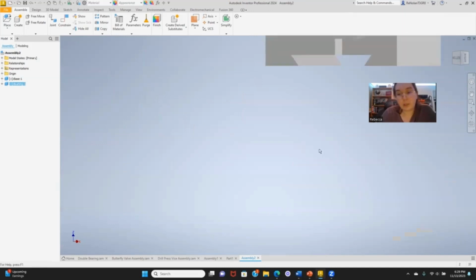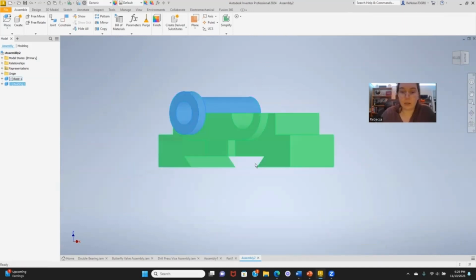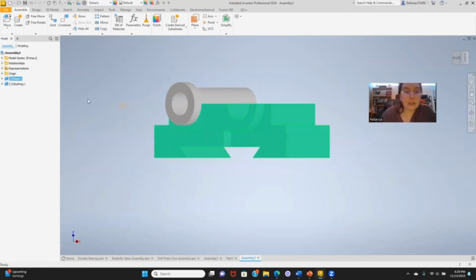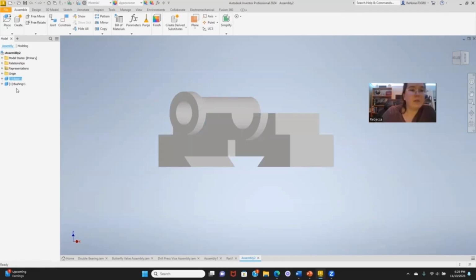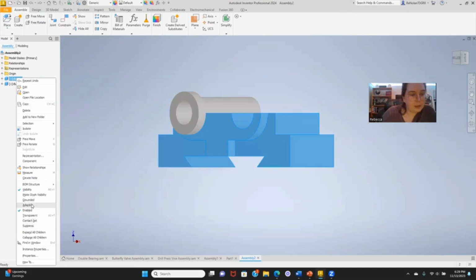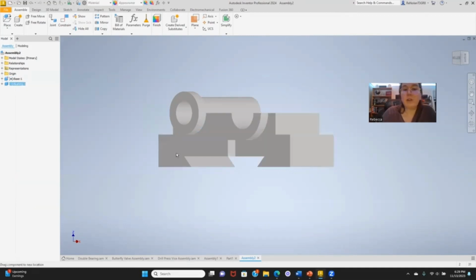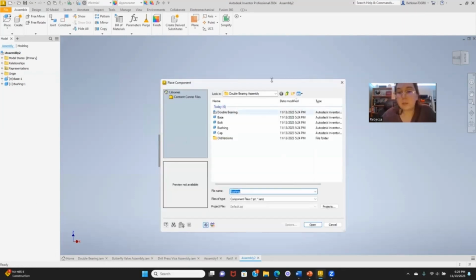And so I go to click the part and drag on it, and it's just dragging my whole system, and I can't effectively test it. Whereas if I were to ground my base, then I can pull on these parts and make sure I've grounded them effectively. So basically, we're going to piecemeal it together to create grounding.